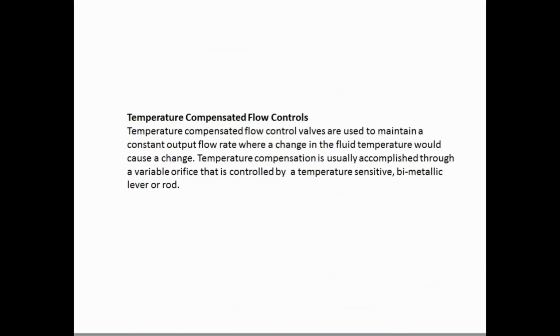Temperature compensated flow controls. Temperature compensated flow control valves are used to maintain a constant output flow rate where a change in the fluid temperature would cause a change. Temperature compensation is usually accomplished through a variable orifice that is controlled by a temperature sensitive bimetallic lever or rod.